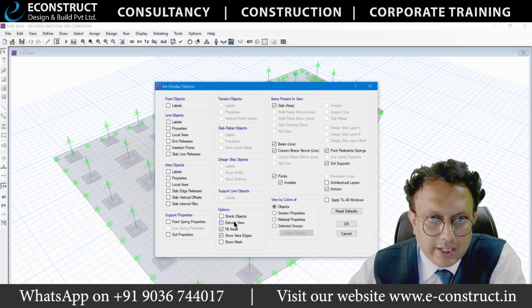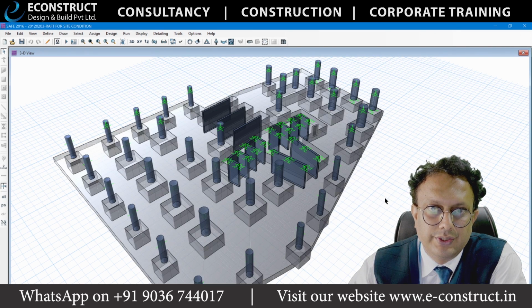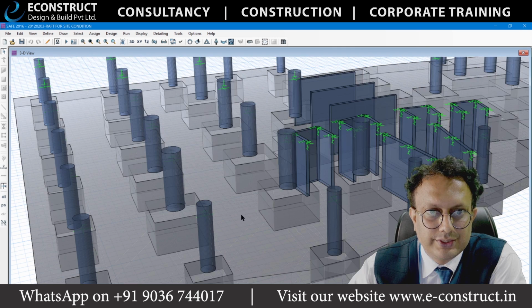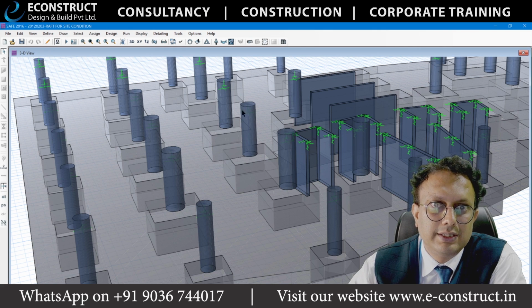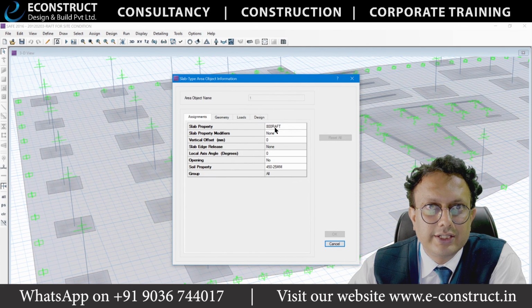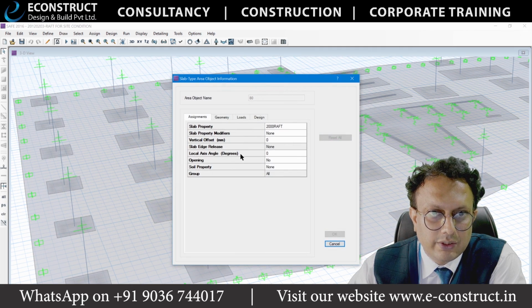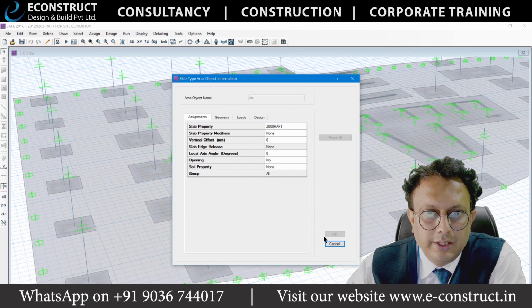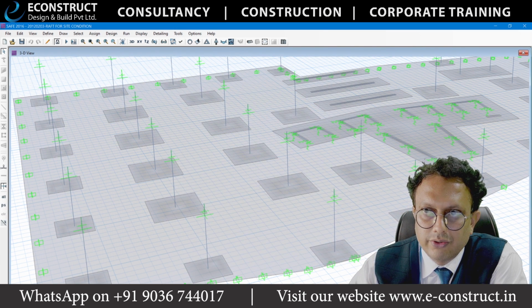So if you just go here and see the extrusion here, this is the extrusion of this. You can see the thickness of the raft and a little bit more thickness of the drop panels. If you right click it here, you will see that the raft thickness is 800 mm, and over here the raft thickness is 2 meters. Meaning to tell you that the foundation would be something like this.